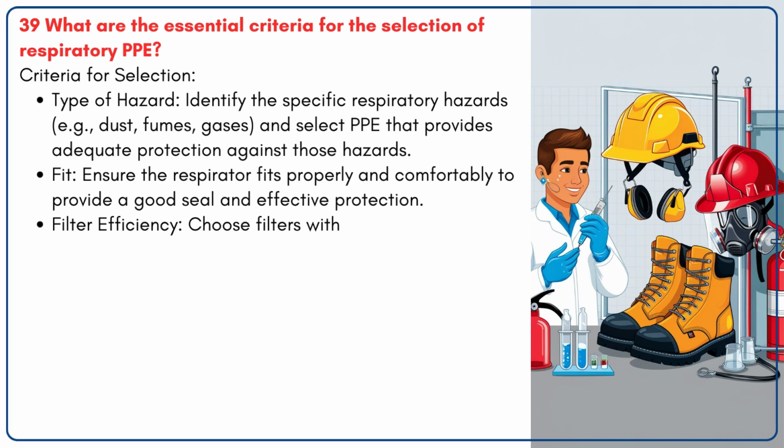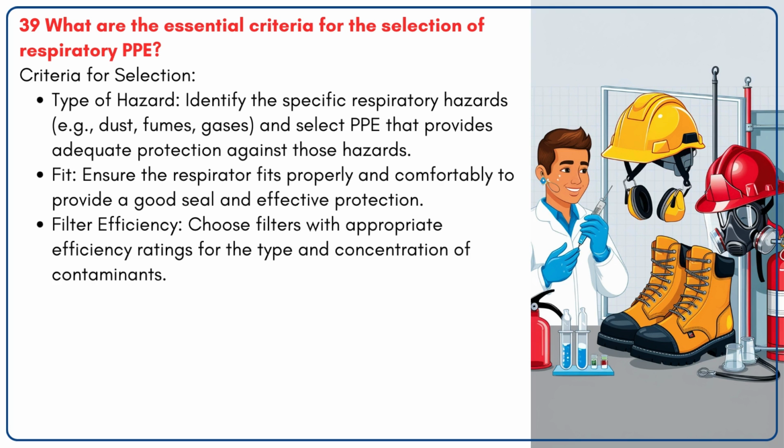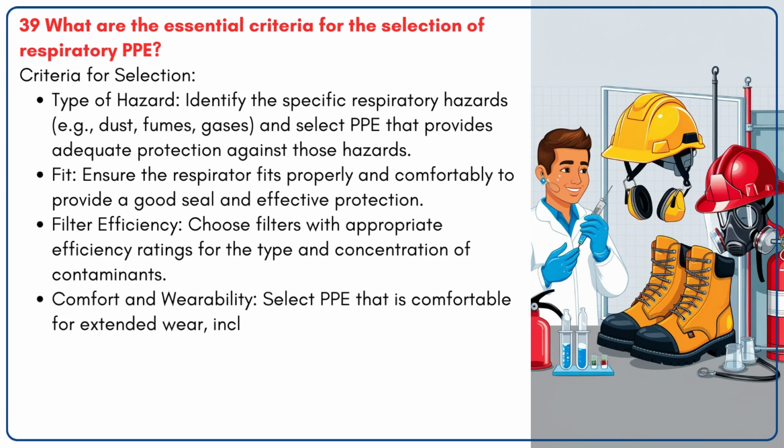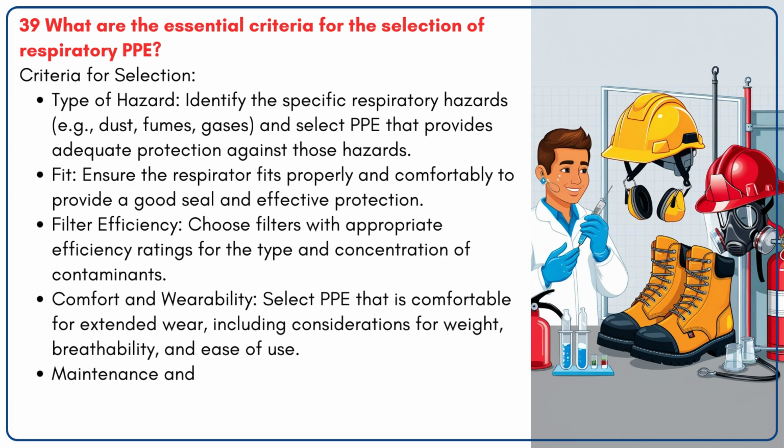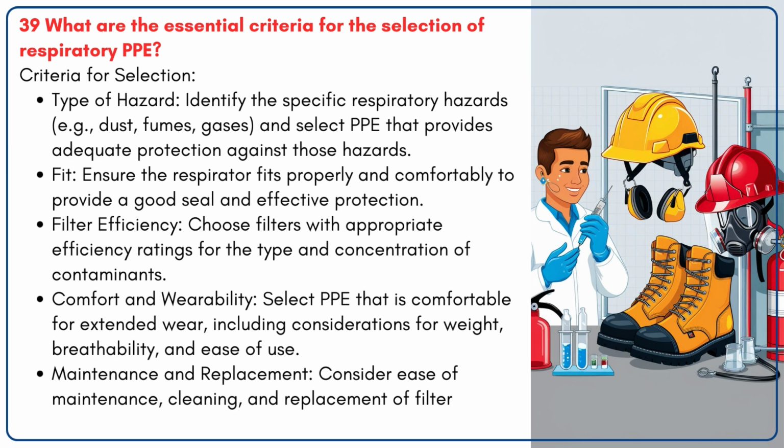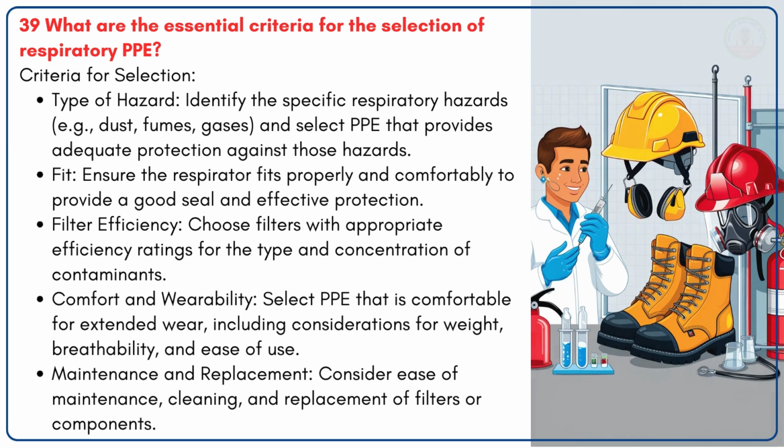Filter efficiency. Choose filters with appropriate efficiency ratings for the type and concentration of contaminants. Comfort and wearability. Select PPE that is comfortable for extended wear, including considerations for weight, breathability, and ease of use. Maintenance and replacement. Consider ease of maintenance, cleaning, and replacement of filters or components.